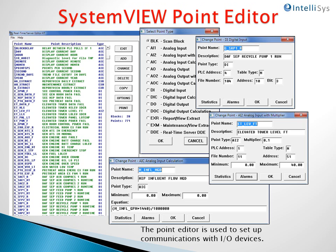Several point configurations are shown here. The digital input for a DAF separator recycle pump 1 run signal, basically a DI or digital input, showing the address and other information. And there's also an analog input, AI2, with scaling, and this is an elevated tower level. We can see that the elevated tower level has a multiplier or scaling of 0.1, so we're multiplying times 0.1 the value we read out of the PLC.